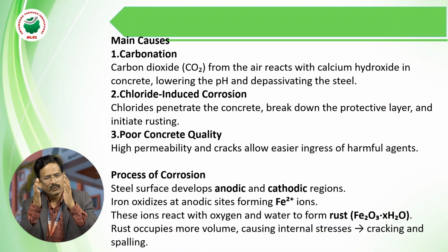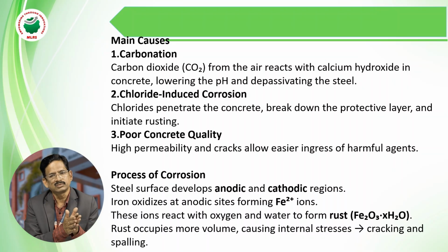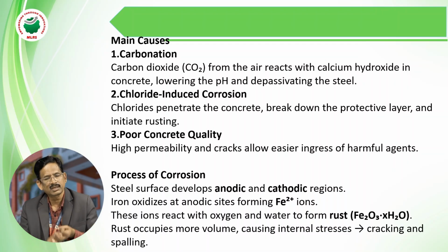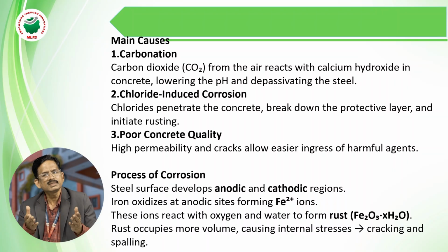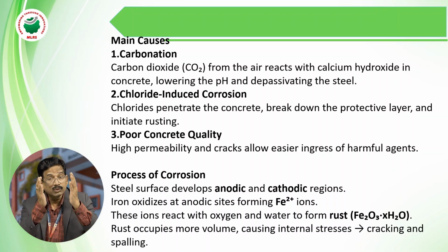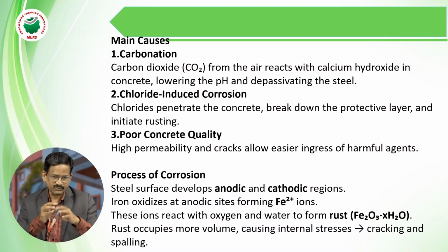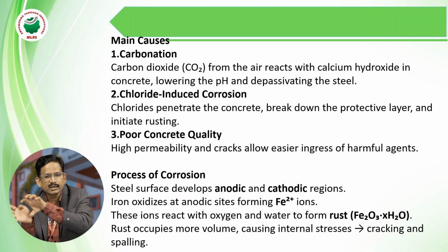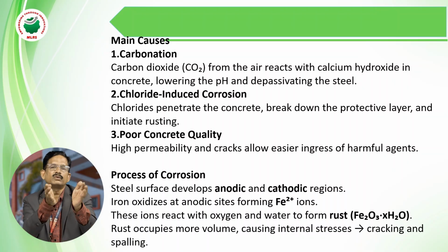So that's why we have to test all the materials. We test cement separately, fine aggregate separately, coarse aggregate separately. Water is also tested; only drinking-quality water is used. If the water has salts or the pH is less than 7, that will be harmful to the concrete and also to the reinforcement. So what I am trying to tell is that corrosion of the steel reinforcement is also caused by the impurity of the water.